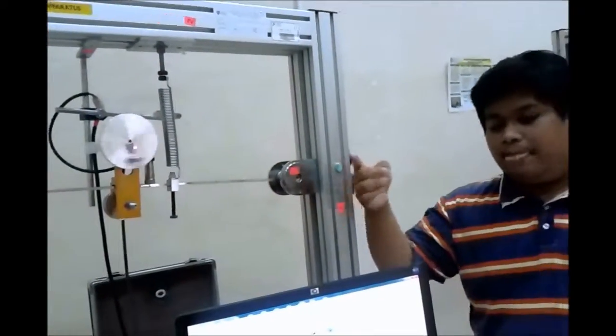For the tachometer to take the data of the rotating shaft in RPM or RPS, the laser beam has to be reflected to the shaft and back to the tachometer to read the data. And for doing that, the shaft has to be pasted with a reflective mark, using a reflective tape or something that will reflect the laser back. And in this case, it has a reflective tape that will reflect the laser back.